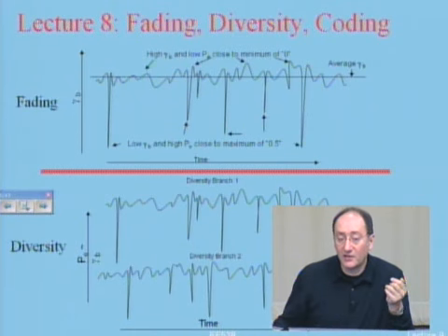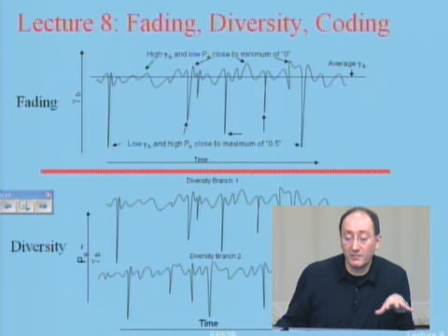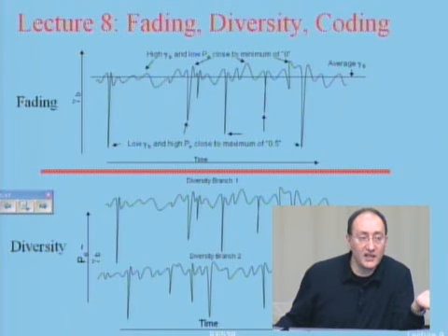If they add together, I have a very strong and healthy signal. So my problem in radio channel, in multipath radio, is that once in a while, the paths are coming against one another and they cause fading. What will happen when we go to the fading? My error rate goes way up. What is the highest error rate that you can have? It is 0.5.